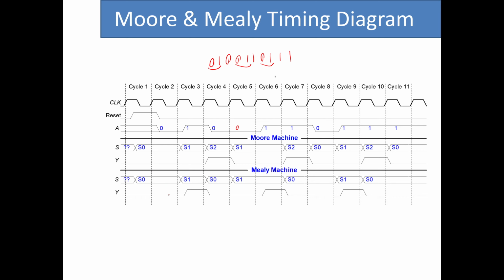and also the output logic unit, as you can see, if I want to highlight this, you see the output of the Moore FSM becomes true later than the output of the Mealy FSM. So the output of the Moore FSM is completely synced with the positive edge of the clock. But the output of the Mealy FSM is not. And that is because we have this extra path that goes directly from the input to the combinational logic circuit that is calculating the output for us.